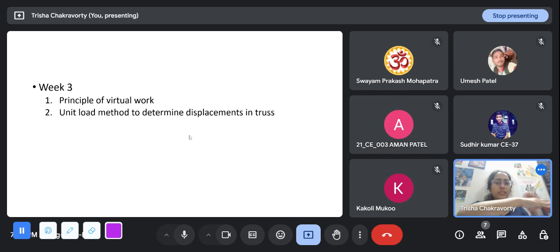So, for example, imagine there's a beam, and we are loading it with a uniformly distributed load. What happens is, this is a transverse load. So in the beam there is a bending moment generated and a shear force generated. So the bending moment and the shear force make a stress develop in the beam section. So that is the force or stress related response.